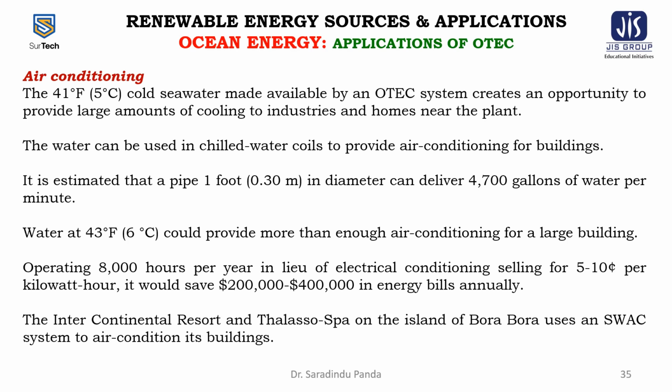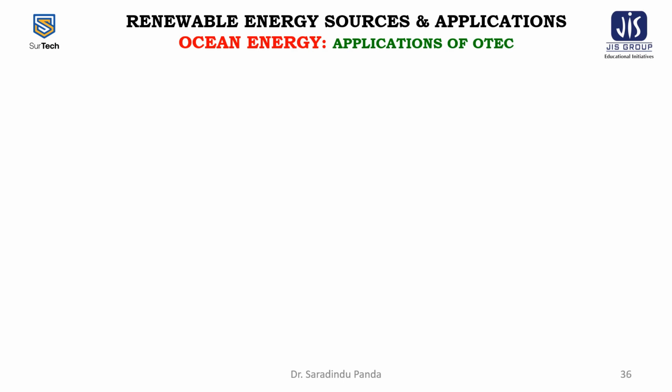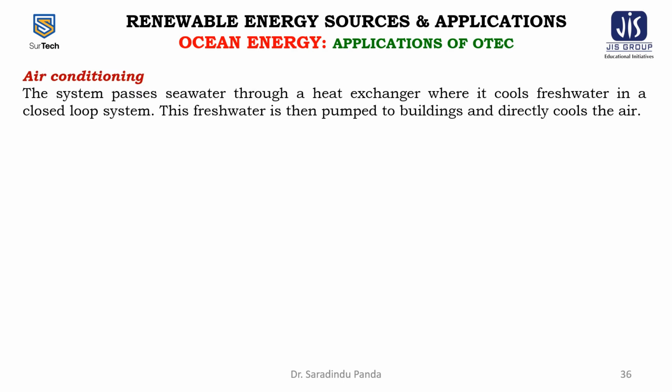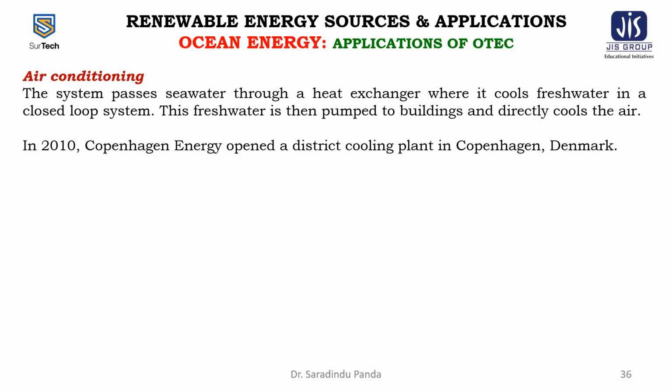The Intercontinental Resort and Thalasso Spa on the island of Bora Bora uses a SWAC system to air condition its buildings. The system passes seawater through a heat exchanger where it cools fresh water in a closed loop system. This fresh water is then pumped to the building and directly cools the air.